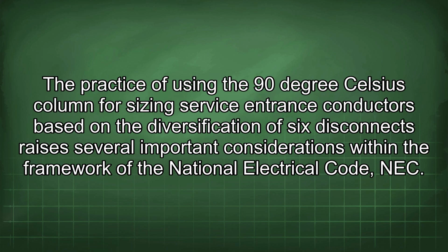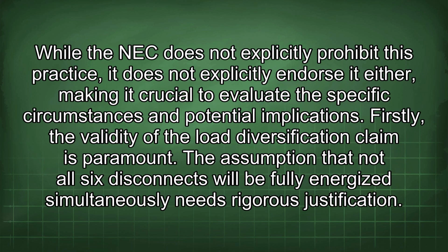The practice of using the 90°C column for sizing service entrance conductors based on the diversification of 6 disconnects raises several important considerations within the framework of the National Electrical Code, NEC. While the NEC does not explicitly prohibit this practice, it does not explicitly endorse it either, making it crucial to evaluate the specific circumstances and potential implications. Firstly, the validity of the load diversification claim is paramount.